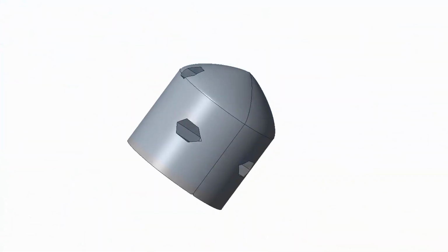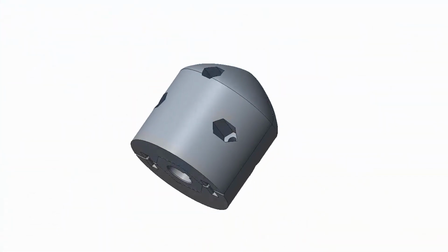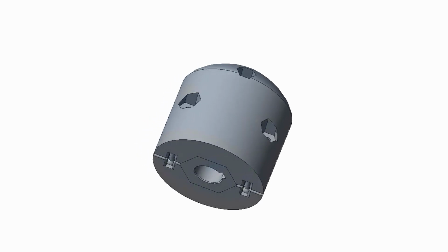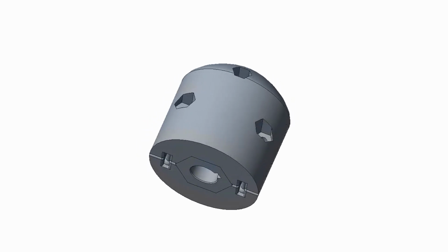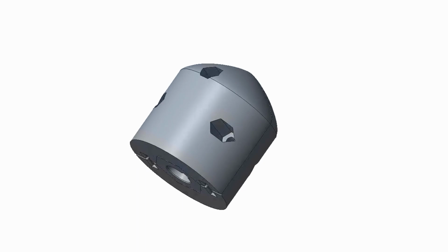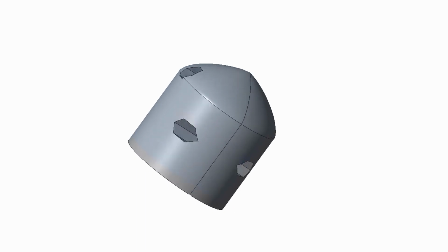The nose cone plays an important part in the performance of the turbine. Hence, we used the formula governing the Haack series shapes for nose cones developed by Wolfgang Haack to determine the optimal shape. 3 screws were used to join both halves of the hub together securely. However, in order to have sufficient surface area to fit the thick blade roots and screws, we had to compromise for a more blunt nose.